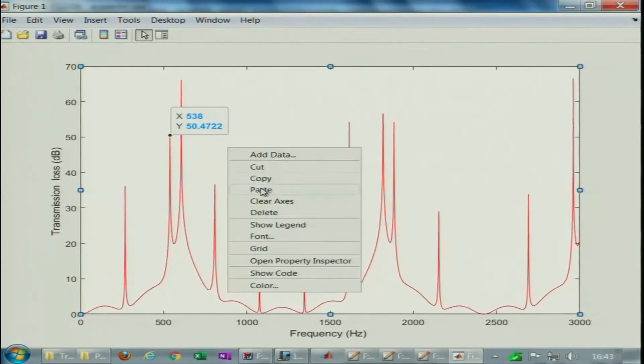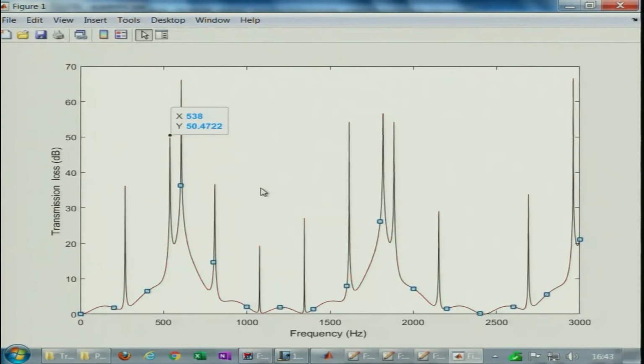So, this is what I have taken out and pasted it again. We are getting multiple resonances due to destructive interferences, and there are some troughs also occurring because of constructive interference. There are frequencies at which the entire acoustic power is transmitted as it is. These are all part of multiply connected mufflers, and there are a large number of such connections. For example, what I am going to probably talk about in the next class perhaps are a few connections which are much more intricate, much more complicated.